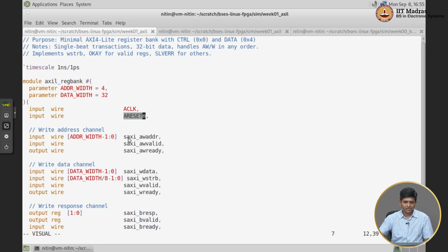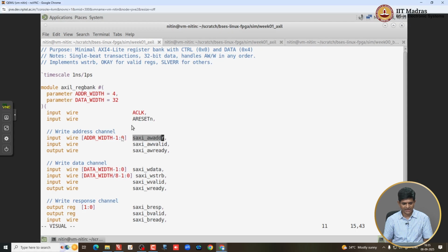By default, there is also the convention that the names of the wires also tend to be in capitals, but there was some problem with Cocotb where it does not recognize some parts of the signal automatically if you use capital letters, which is why I have renamed everything using lowercase letters out here. But let us look at the overall set of signals that we have.